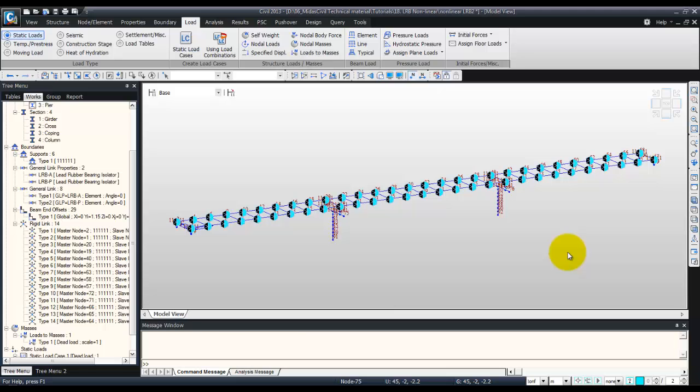And in order to reflect the dead load in the time history analysis, the time varying static load function is used. This function basically creates a condition in which the dead load is in place at the time of performing the time history analysis for the seismic load. So I will create a ramp function and assign it to the static dead load, and the El Centro data which is used for the seismic load will be created afterwards.